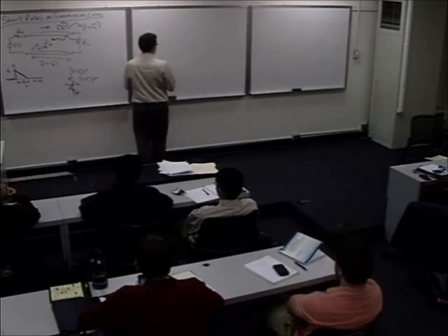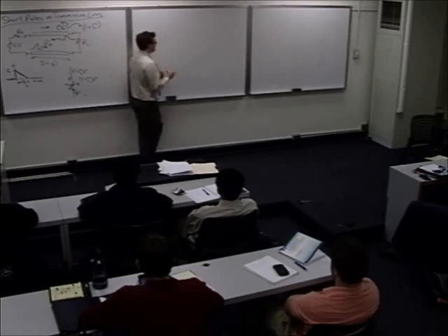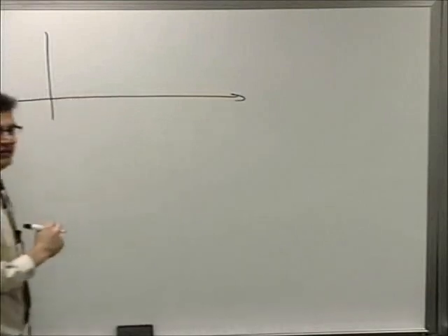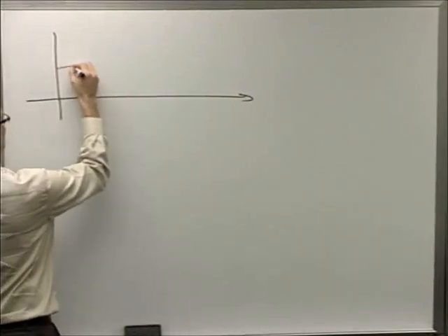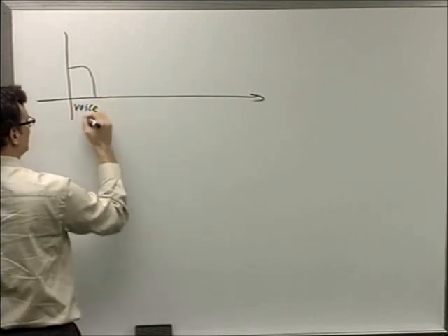Well, they had to hide a data signal on it. They had to do it in such a way that it wouldn't disrupt your voice, and all of those reflections at the transmission line wouldn't disturb it. So if you look at the Fourier transform of what's going on your telephone wires, there's still a portion down here that's reserved for voice at the low frequencies.